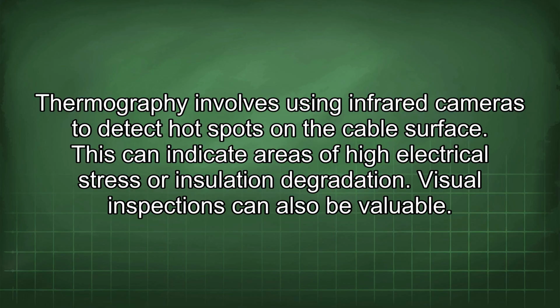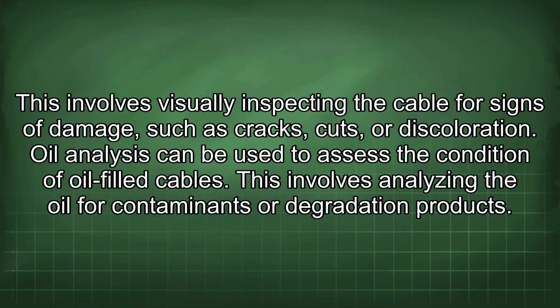Thermography involves using infrared cameras to detect hot spots on the cable surface. This can indicate areas of high electrical stress or insulation degradation. Visual inspections can also be valuable. This involves visually inspecting the cable for signs of damage such as cracks, cuts, or discoloration.